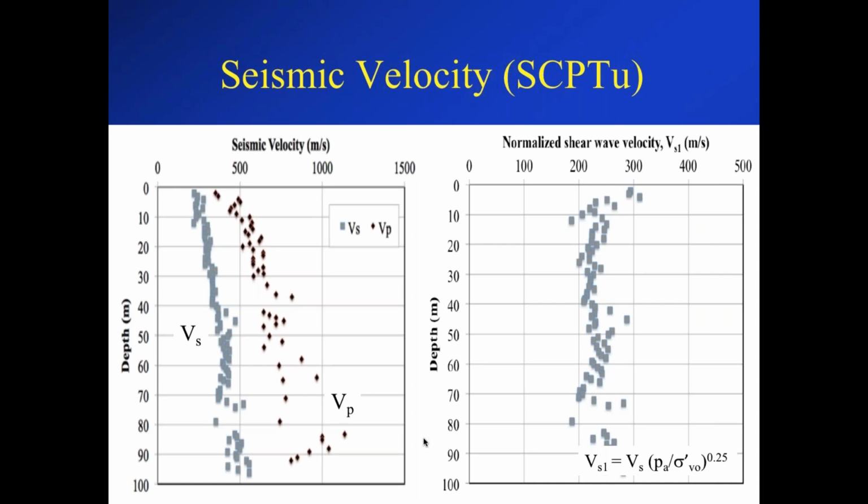And with the P wave velocity, it's similar. It's a downhole method, but this time they're usually hitting something vertically. Sometimes it's a plate placed on the surface. Sometimes it might be a small auger installed into the shallow surface and then hit vertically, and that generates a compression wave that travels down. Again, if you do it at one depth, you would get the average compression wave velocity, but if you repeat it every meter, then you get what's referred to as the pseudo time interval as you calculate the velocity. And here you can see the scattering; the P-wave velocity does increase fairly significantly with depth.